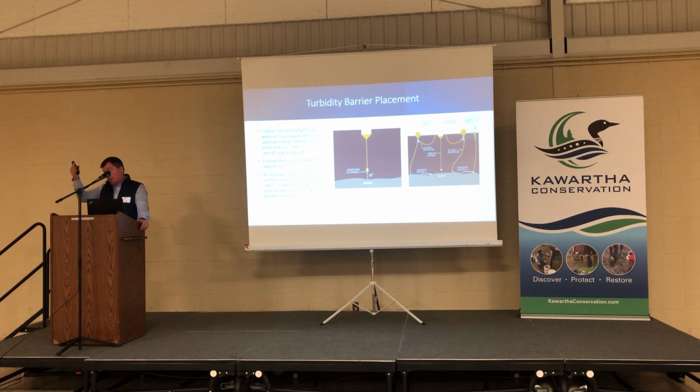The issue, if it is sitting on the bottom, is silt can build up on it, or if you get a heavy wind or a wave event, that curtain will actually drag on both sides. And then we get the phone call saying, there's more sediment now than there was before the curtain was installed. Why is that? This is often a good reason. And as we know, all water bodies vary in depth. There are furling lines, which are essentially ropes that extend from the bottom all the way through the top float, and allow us to cinch that curtain up just enough off the bottom so it doesn't disturb the sediment.